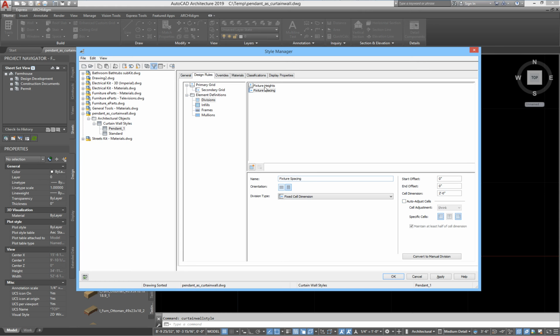So that's the vertical. Let's go to the horizontal spacings. Now these are going to need to be done manually, so set this to manual. I'm going to set a distance from the top. This distance from the top is going to be the height of my ceiling mount block, which is that 3D, basically a cylinder that's screwed to your ceiling, your sheetrock. Mine happens to be 2 5/8 of an inch high. So I just know that. You would have to set whatever number yours is in there.